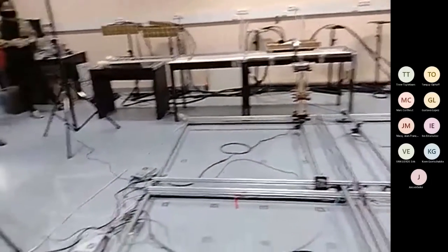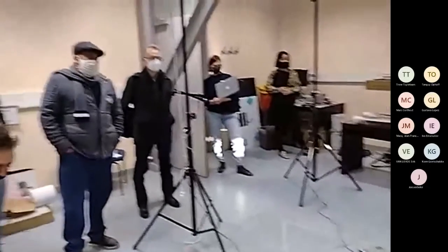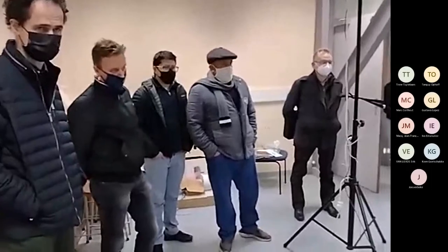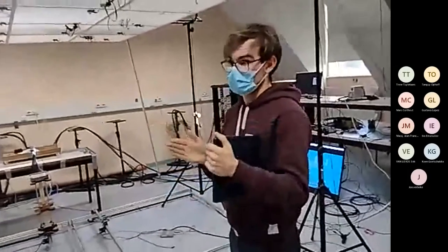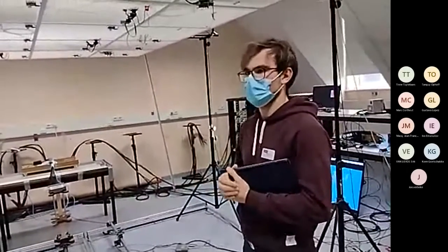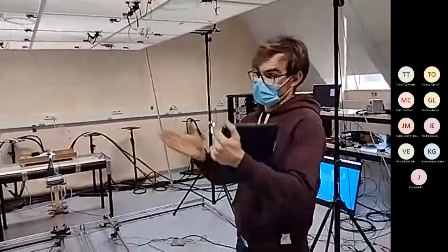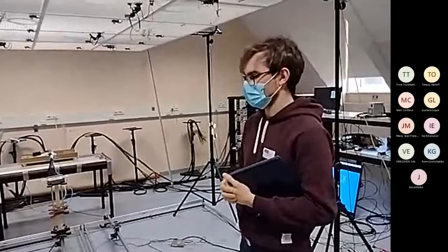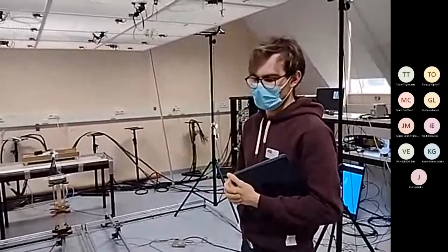But in the context of 5G, for example, there are other bands that have been opened up, like 3.5 gigahertz, which is a much lower frequency, but that signal is much more robust. You can also do some beamforming there. The antennas are quite a bit smaller than for the 1.8 gigahertz. And with beamforming there, you can also point towards the user in the air, for example.